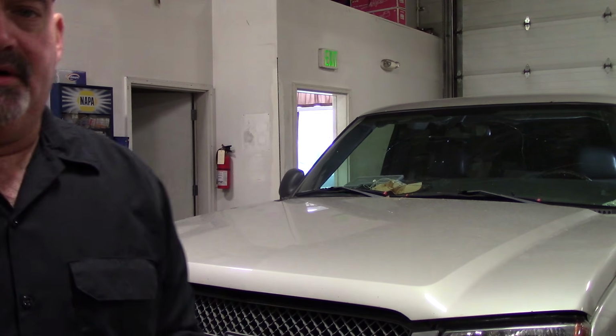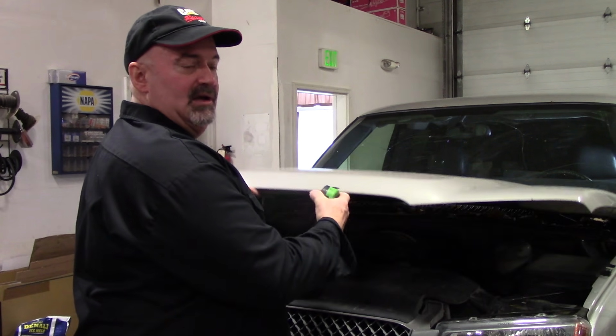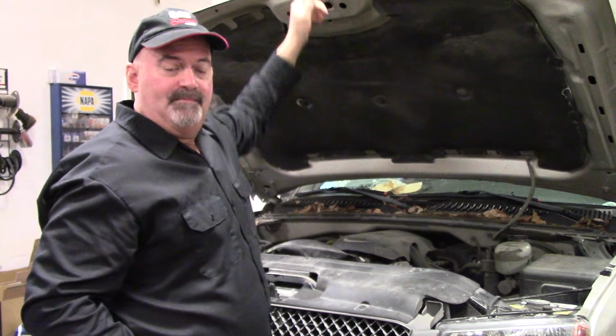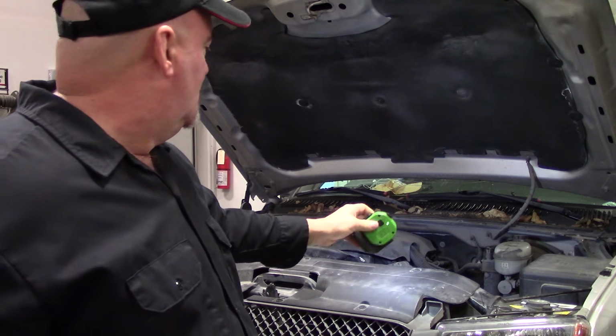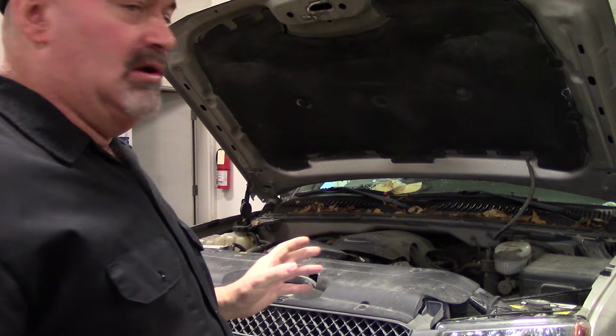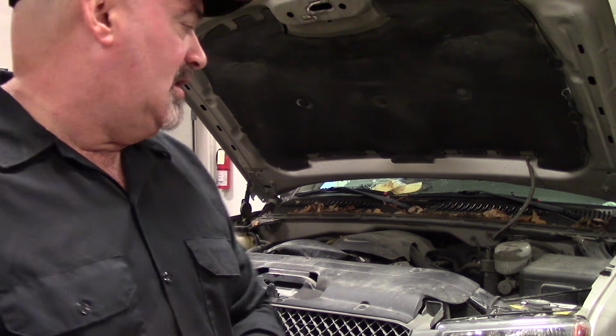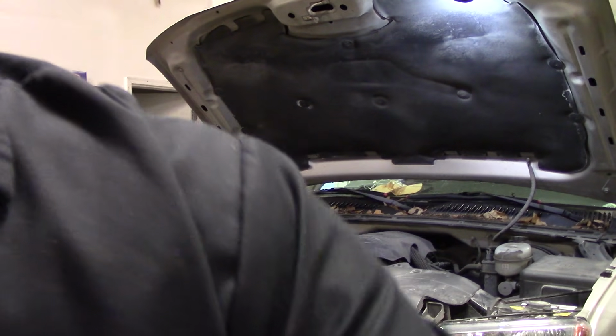So we'll take a different diagnostic tree as a result. So now we start looking at powers and grounds, and there's a couple common things under the hood that could be a quick check that may identify the issue. There's two grounds on the back of the motor and this main battery ground that you want to look at, because that could definitely cause a lack of power to the panel and subsequent lack of communication.